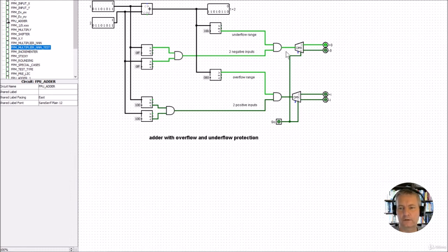But it doesn't tell us whether it's going to be plus minus 0 and plus minus infinity, but we can generate that quite easily. All we do is we take the signed output for the multiplication, and we can just put this through a couple of demultiplexers. If I click on that, you'll see it's a demultiplexer. So it takes that one input and it gives us two outputs, and the two outputs are decided on by this value here.